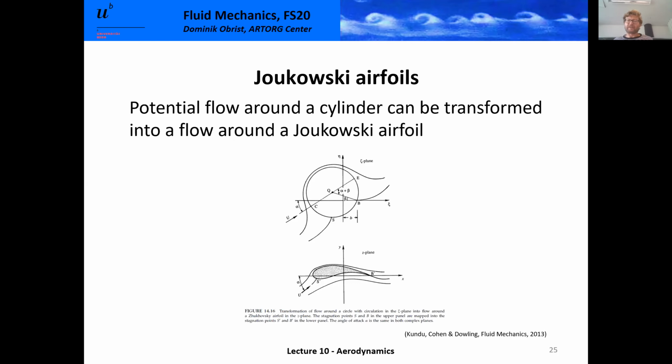So I find this really fascinating that at least for this family of Joukowsky airfoils, you can very quickly and quite accurately, of course with the limitations of potential flow theory, predict the streamlines around airfoils.